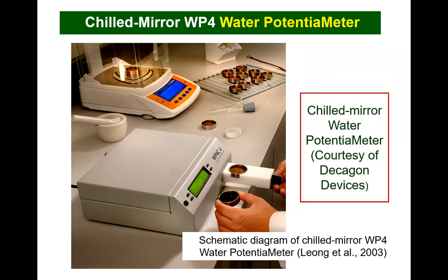The short time required for the measurement of total suction has made this device a popular laboratory device for measurement of total suction. The device appears to give reproducible and accurate results in the range of total suctions from 1,000 kilopascals to near 1 million kilopascals.